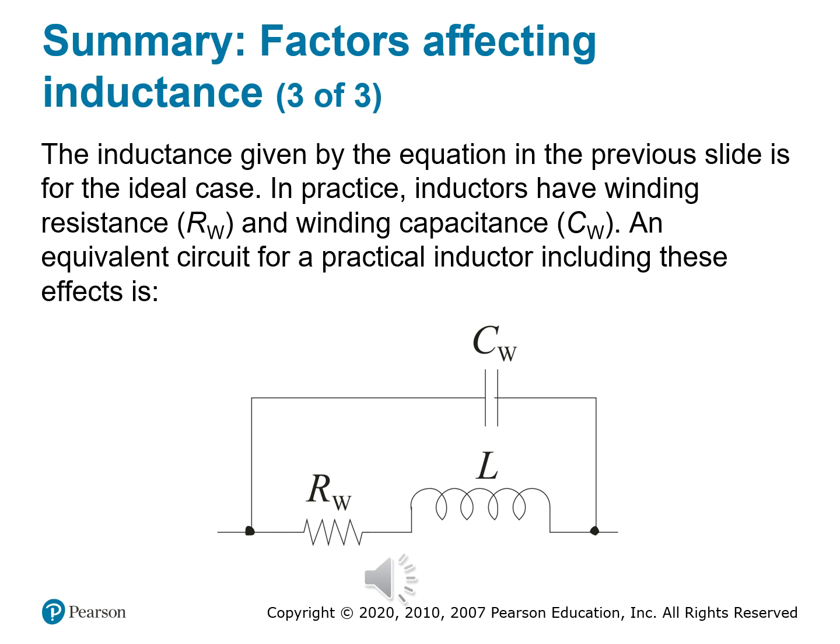When you're designing filters, switch mode power supplies, or tuned circuits, don't just drop an L and walk away. Think of R sub W, think of L, and then think of C sub W, that capacitive leakage. And that's your real inductor.